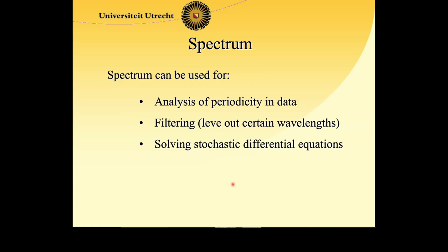So you get the mean and the covariance of the hydraulic head, for instance, as a function of space and time. To solve that analytically, often one reverts to a spectral representation of the underlying random function of hydraulic conductivity. That's also in the syllabus, and we will see that later.